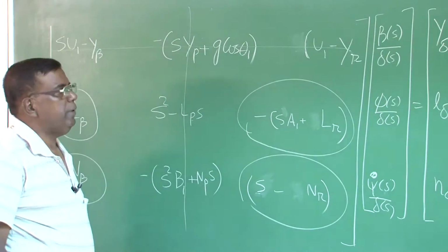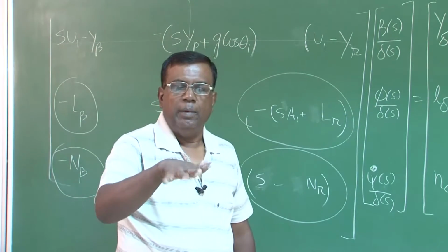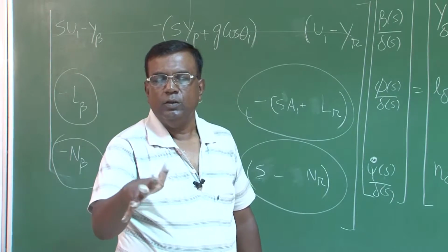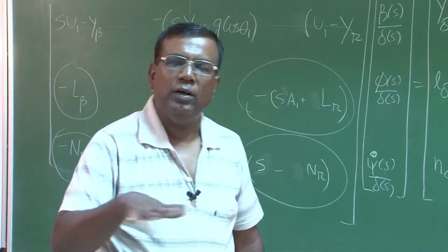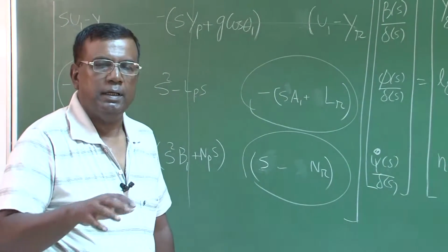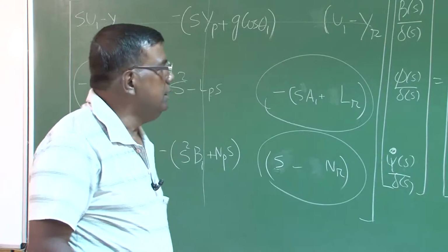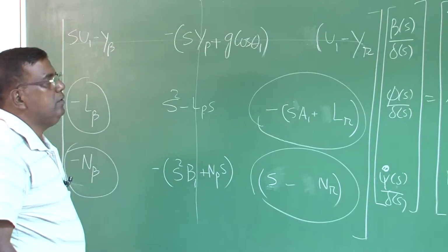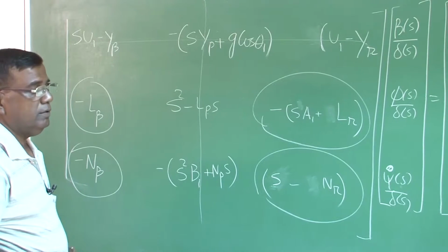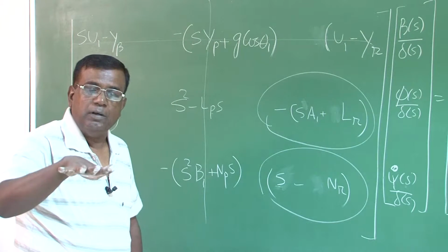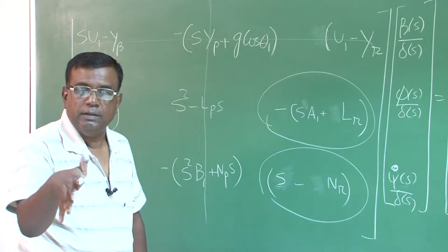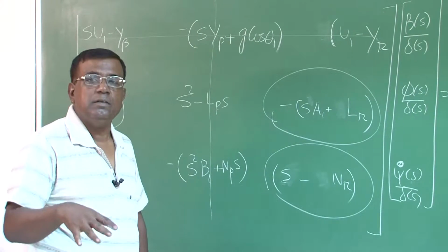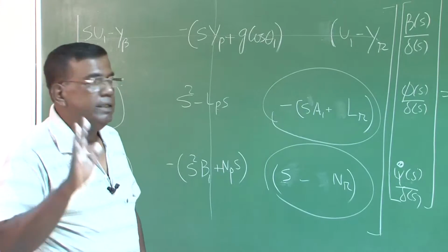Because I am saying in a spiral mode, what I am focusing is bank, side slip, this, further bank, like this. So I am neglecting the effect of any force acting on the y direction. Again, this is an approximation, right? I am more talking about the angular motion. Okay? So this is also dropped as if it is taken care of, or not so important. This is an approximation because when I talk of spiral mode, I am talking about bank, side slip, this, further bank, like this. And though there will be a slight force in the y direction because beta is introduced, in a transient manner, we are neglecting that. Okay?